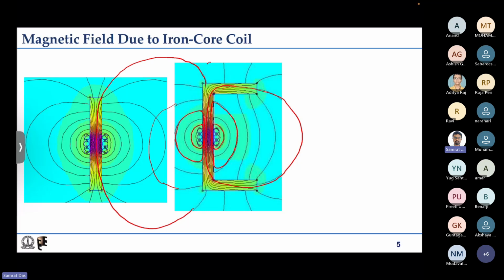Going to the next part of the question, the total flux lines coming out of the iron is equal to the total flux lines entering the air gap. That is true, but because in the air gap, or basically in air, the flux lines tend to get distributed, the flux lines per unit area, that is the flux density, reduces in the air. Because iron is highly permeable, all the flux lines are very densely packed within the iron.